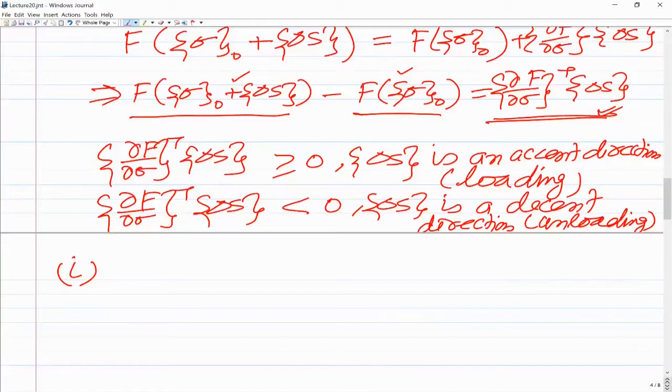Okay, sir. One more thing: here we have written, if the previous step was elastoplastic. While implementing this in code, how will we deal with this? You have to have a flag array, which will be two-dimensional: one dimension is the number of elements, the other is the number of Gauss points in each element. Then you will store, say, one for elastic and two for elastoplastic.